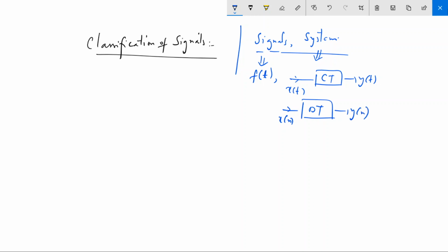Okay, so this is a physical device, but when you say discrete time systems, we generally process continuous time signals with them. Although the signal is continuous in time, we prefer to process this signal using a discrete time system. The reason is that when you use a discrete time system, you have the flexibility that you can implement this system using hardware or you can have a software part also. But in continuous time systems, you have only hardware. There is no counterpart in the software domain.